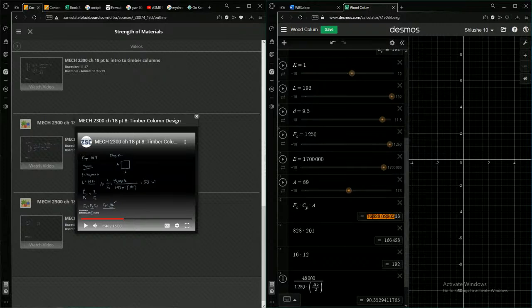76,000. It's way overkill. Let's do a 6 by 16. So 5.5. And we're going to shoot this way up to like... Well, what number would we need? We need 178 area. Nothing has that size. So we got to go up to 7.5. And let's put in the number and we'll see which one's the closest. So we need 60,000 exactly. 93 is the closest. 86 and 101. 101 is 4,000 over.